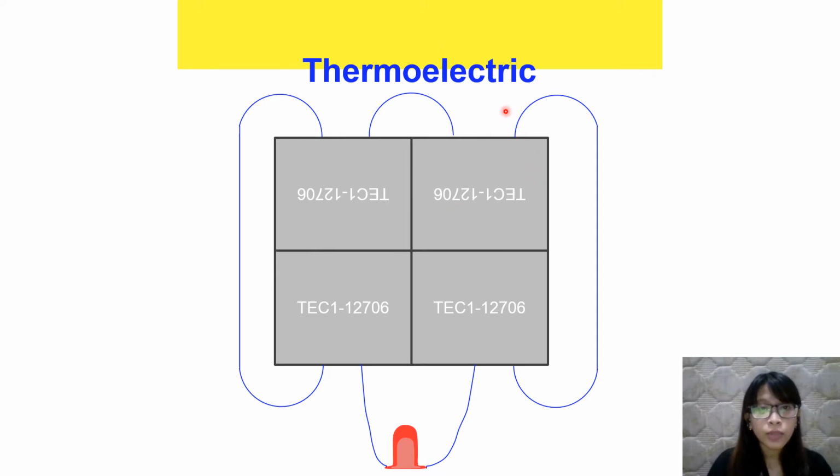So the next step will be to secure all the locations of the 4 thermoelectrics and put all the 4 thermoelectric generators in series by making sure that there is no blank space between them. And then I have to secure them with electrical tape.